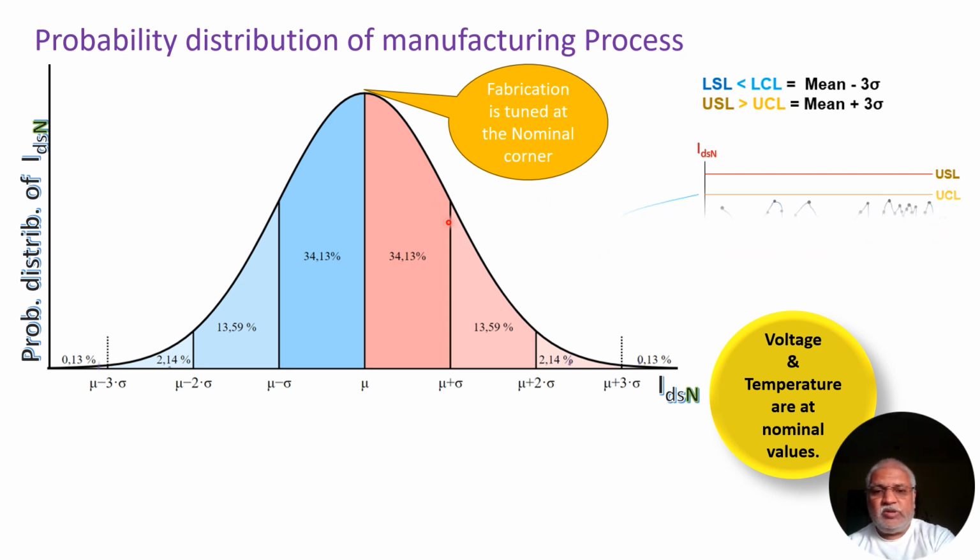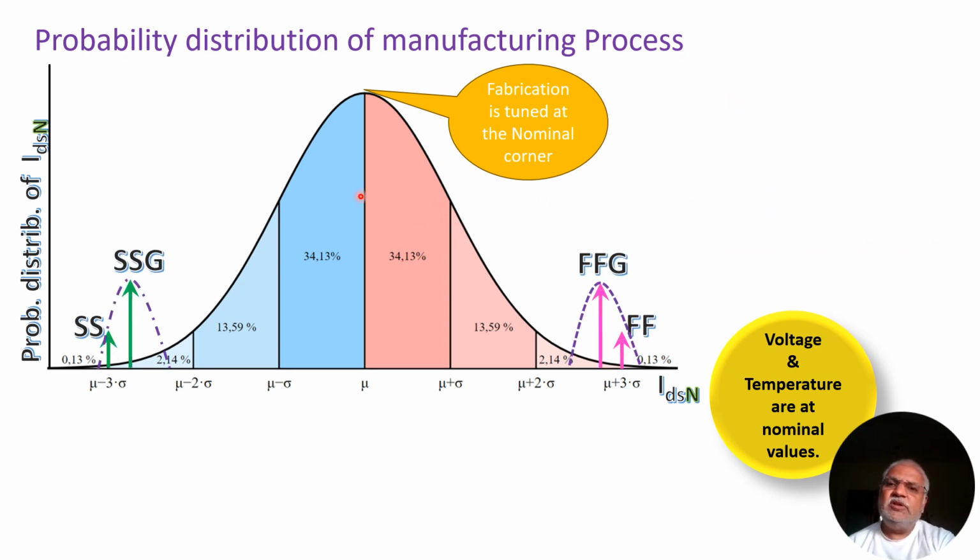So instead of using the performance corners, FF, SS and TT corners, with the OCV derates, they wanted to use the slow global, fast global and typical global corners, and then use other fudge factors, so that the distribution will be symmetrical, and hence they get the best situation out of the simulations.